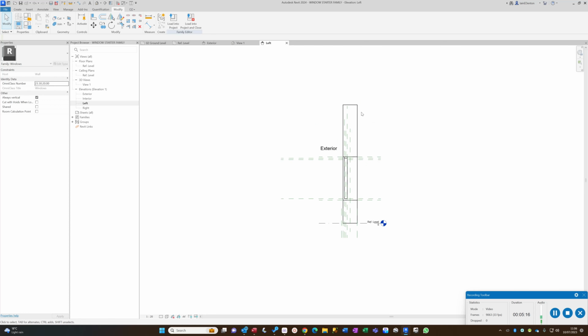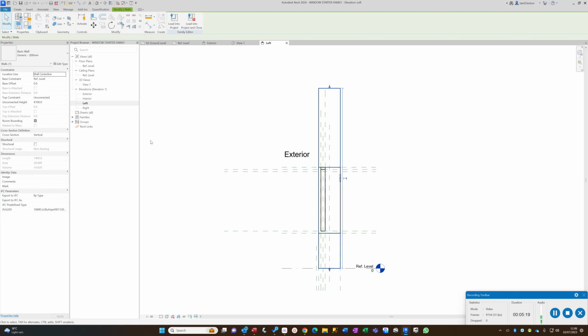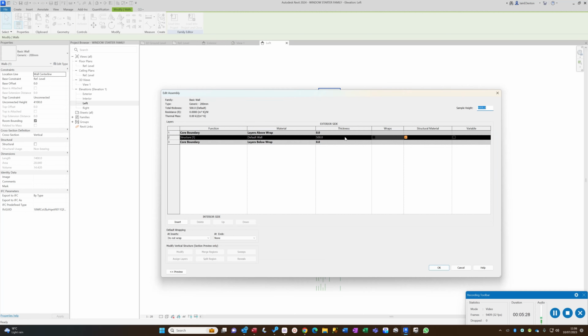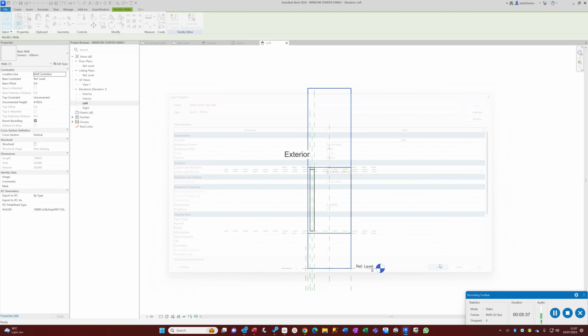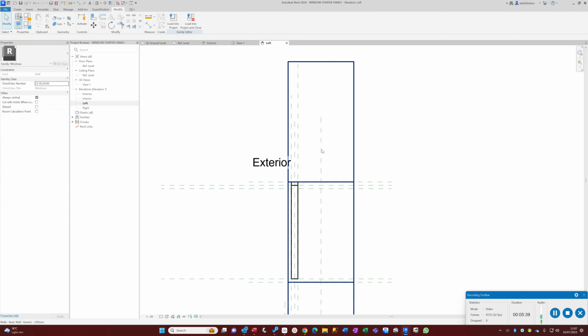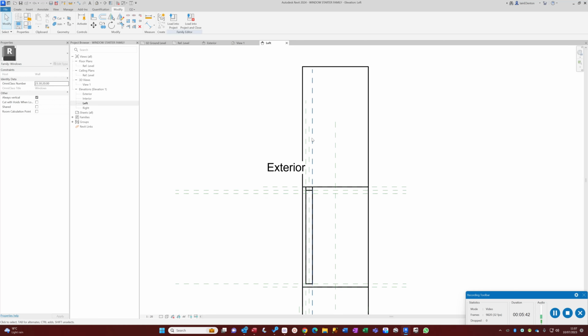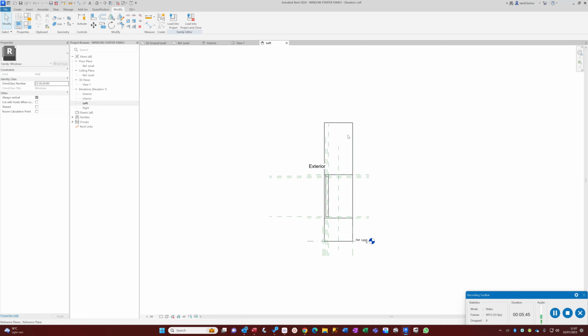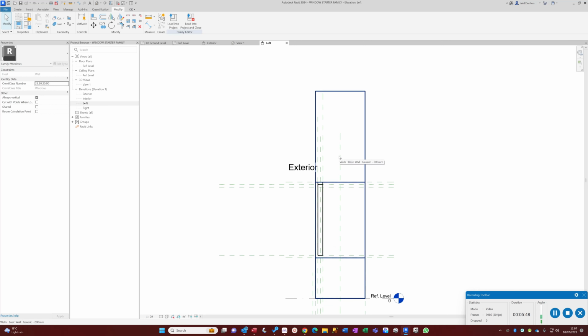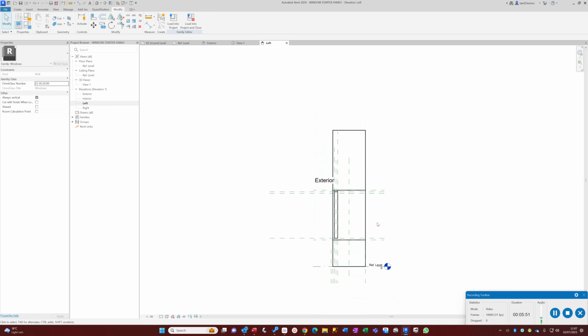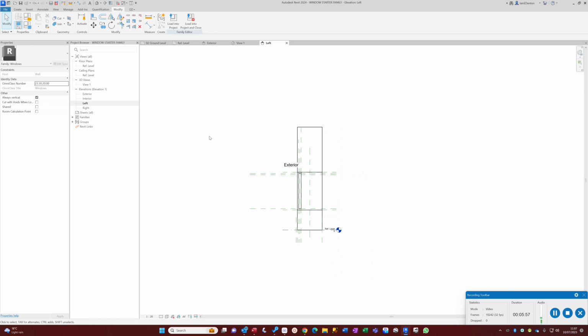And just one tip, this wall, if you go onto the new window template, this wall can be quite thin. I like to click on it, edit the type, and make it really thick. Let's call it a metre thick. And that means that when you're actually drawing these things, you're keeping away from this central point, because you don't want to be locking to that central point. You want to be locking to the point where the window is going to sit. So I always make this wider than it actually should be, so that I'm not locking to that. And if I'm locking to the back of the wall, I want to know that I'm going all the way across. Obviously a wall will be much thinner than this usually when you actually construct.